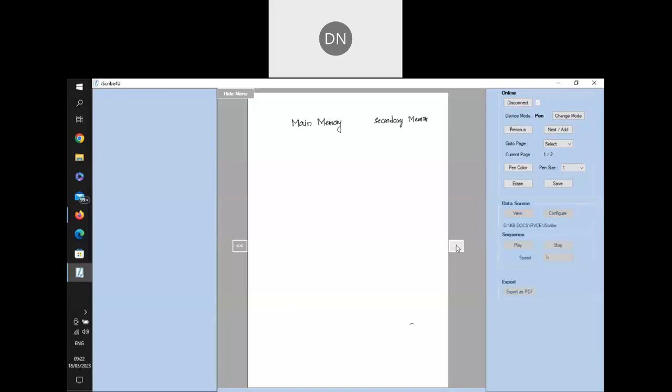We know that any memory which is connected directly to the processor address bus, that means the processor address bus is used to access that memory, is called main memory. Anything which is not connected to the processor address bus, that means whenever the processor generates an address it is not directly mapped to that memory location, is called secondary memory. Secondary memories include magnetic disks, magnetic tapes, and optical disks. Nowadays we also have SSDs, flash drives, and flash disks. These are all types of secondary memory.